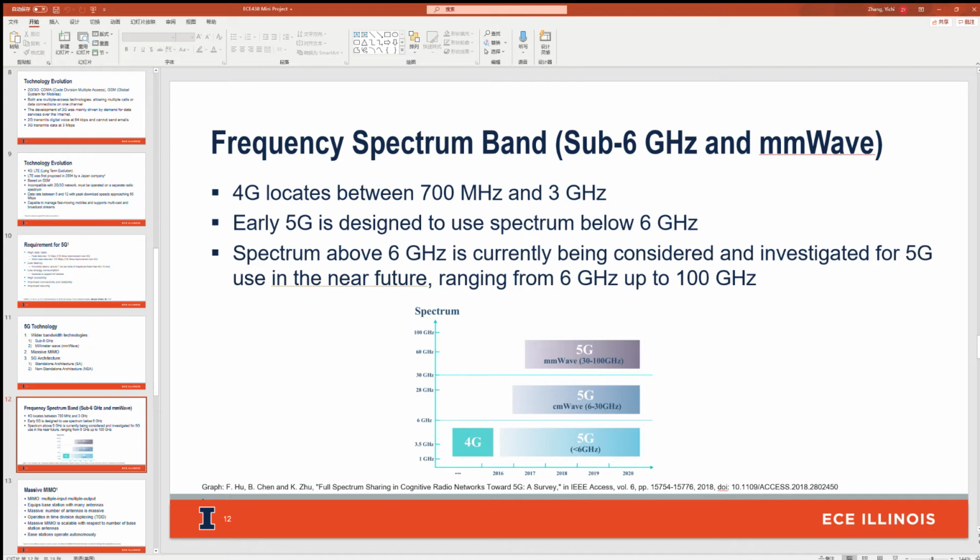More radio spectrum will be vital for the next mobile generation in order to reach the key requirements as proposed before. Consequently, there needs to be an expansion of the frequency bands utilized, which can be obtained with the adoption of new bands and also by using the spectrum more efficiently. As explained earlier, the spectrum utilized for mobile communication is situated below 6 GHz and is saturated. This means it's going to be remarkably difficult to find all the spectrum needed for 5G